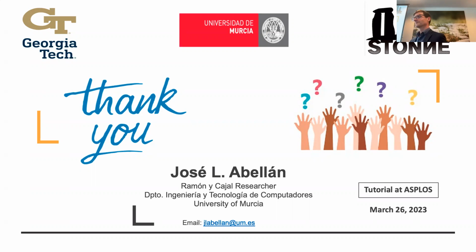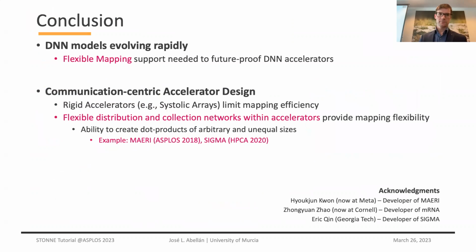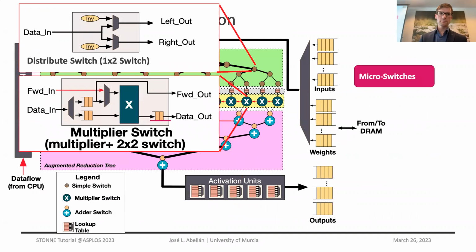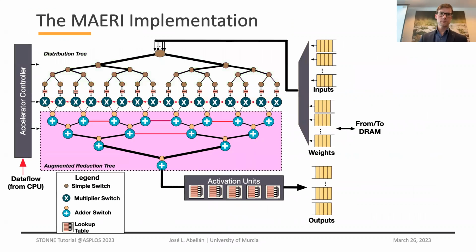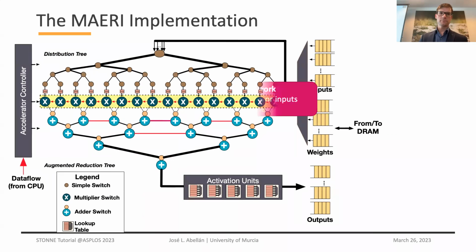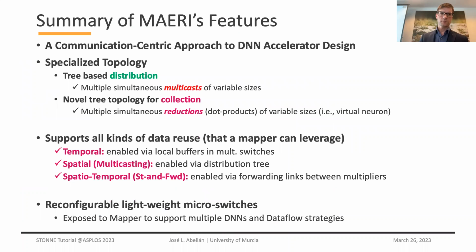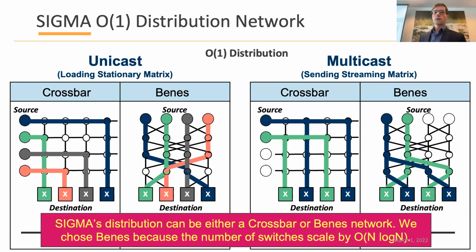Okay, and the latency is not so throughput, of course, like you said, 100% mapping efficiency, so you get a lot of throughput. My question was more about the latency introduced by the networking. So MAERI is basically pipelined. One of the stages is the complete distribution network, and then the multiplier network is one stage of the pipeline. So there are FIFOs between them, which basically enable pipeline operation. And then at each stage of the reduction network, there are FIFOs which enable pipelining. So the latency of an individual stage is not affected.